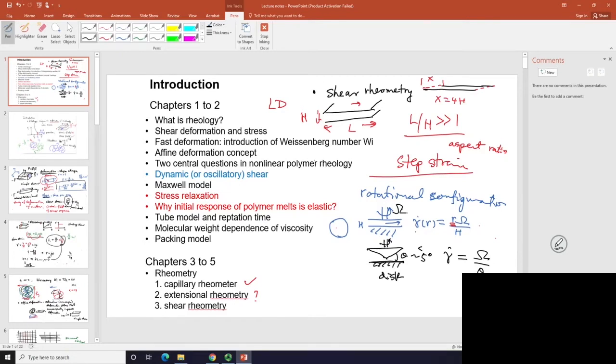What I can emphasize for you is how nasty this kind of rotational shear device could be, because it necessarily leaves the sample with a free surface. Necessarily. Remember, one day I said I want to use saliva with my water to demonstrate. It's the same thing. Basically, the surface tension is holding the sample at the meniscus, so-called. And this is a disaster when you shear very strongly.